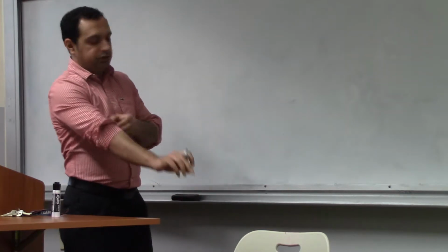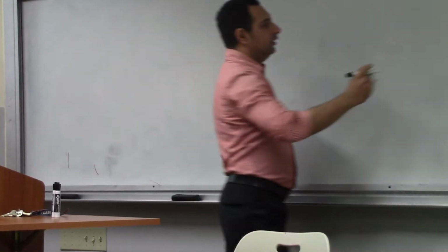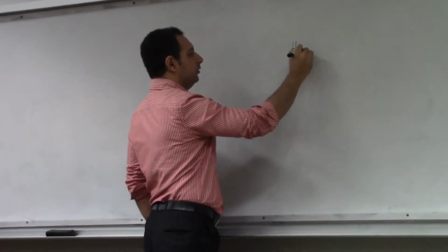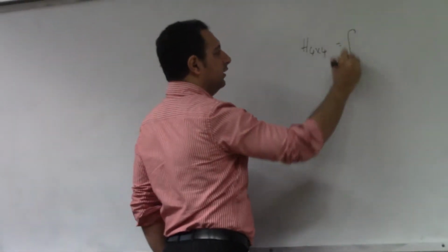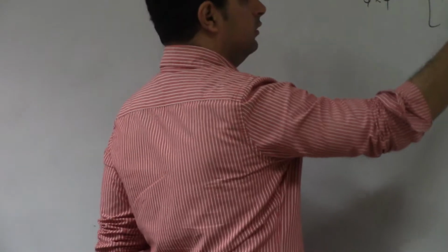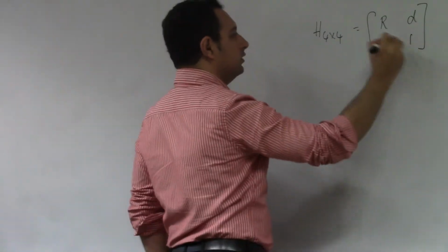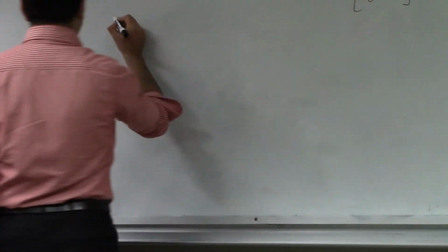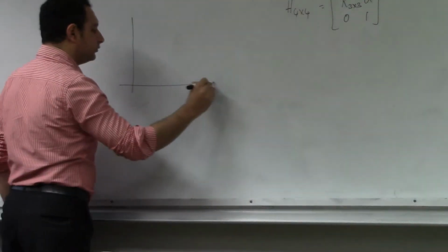define a manipulator structure. Now, if you look at the transformation matrix, the 4x4 homogeneous transform, we said that it is R, B, 0, 1, where R is 3x3. So you can encompass both a rotation and a translation within a single matrix. This is really important because when you look at a manipulator, let's take a very simple manipulator.